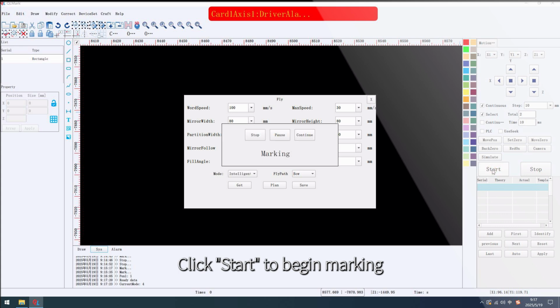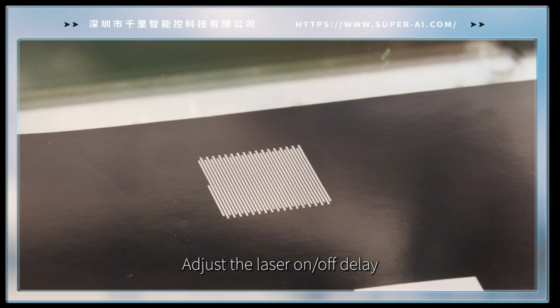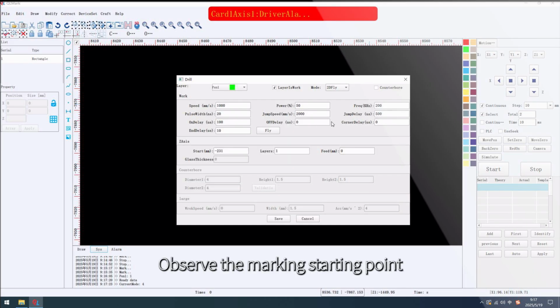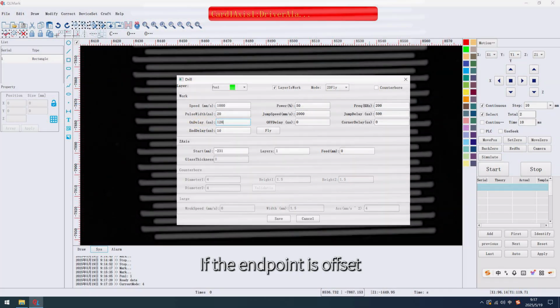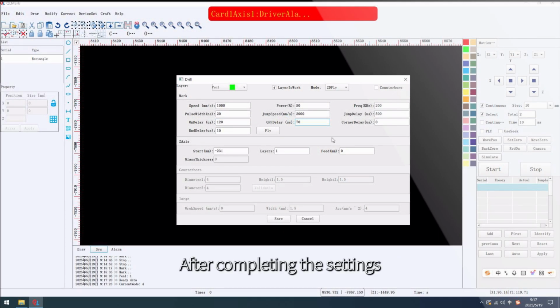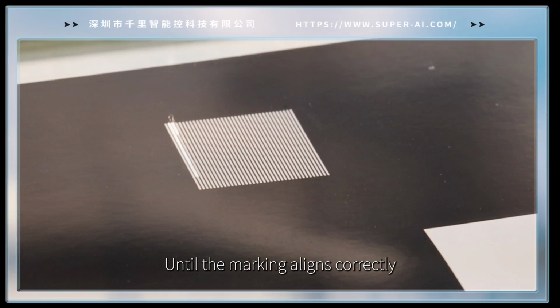Click Start to begin marking. If the marking results are uneven, adjust the laser on-off delay. Open the drilling parameter settings. Observe the marking starting point for left or right offset. If the starting point is offset, increase the laser on delay parameter to delay the laser activation. If the endpoint is offset, increase the laser off delay to delay deactivation. After completing the settings, click Save, retest until the marking aligns correctly.